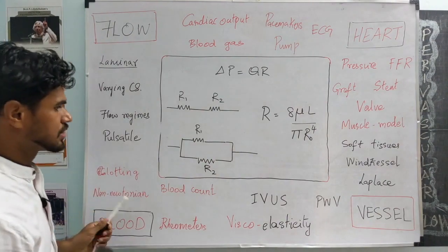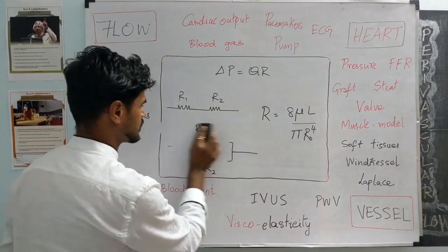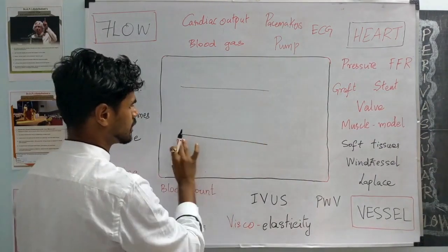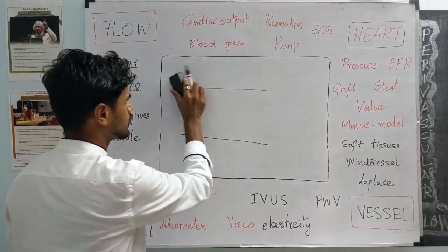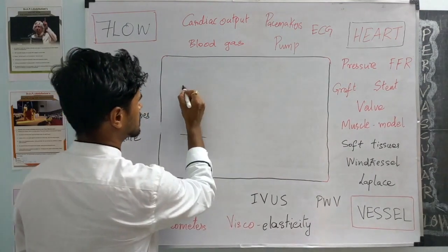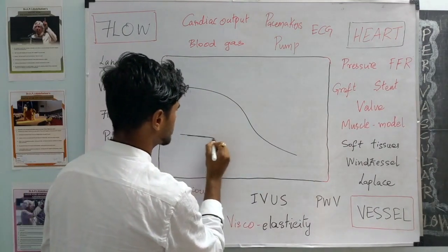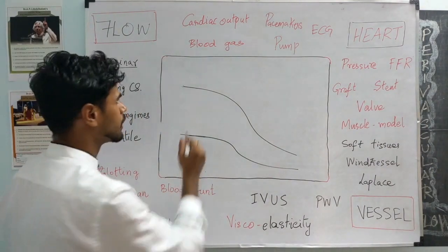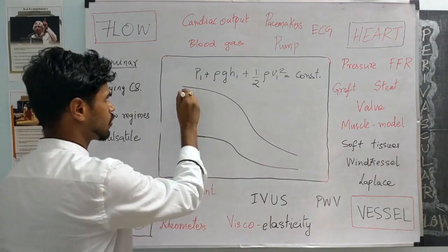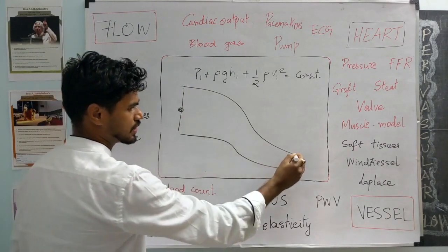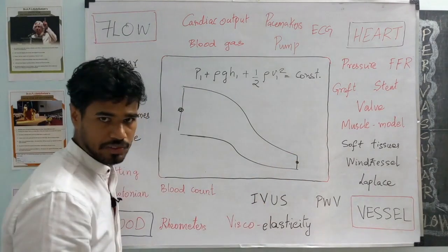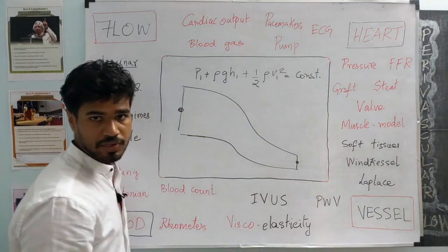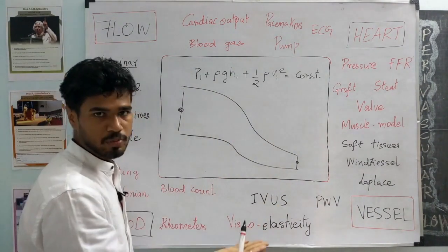The next straightforward generalization from the laminar approximation is to look at a variable cross section. Instead of assuming it to be a straight tube, we are going to assume the tube is of a variable cross section. And the equation that comes very handy in analyzing this situation is the very well known Bernoulli principle. Essentially, in problems involving pressure and velocity at one cross section and pressure and velocity at another cross section, they can be related using Bernoulli's equation, and unknown variables could be easily found.